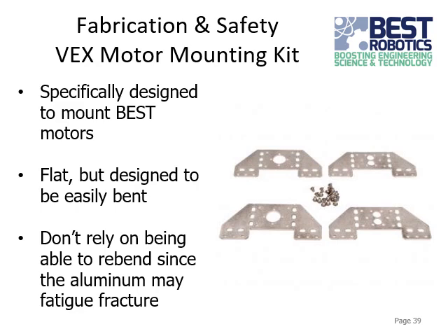are either inward, where the little parts at the very bottom go in towards the motor, or outward, like external, where they bend away from the motor. Outward, if you have the room for it on your robot, is usually easier because that means you can get to the screws and screw those screws on the mount without having to take the motor on or off. Because if they're inward, then they're kind of hidden underneath the motor, so you'd have to take the motor off first. But if you bend it one way and you decide you want the other way, then it's too late. You can't really rebend it. You're kind of stuck with what you got at that point.